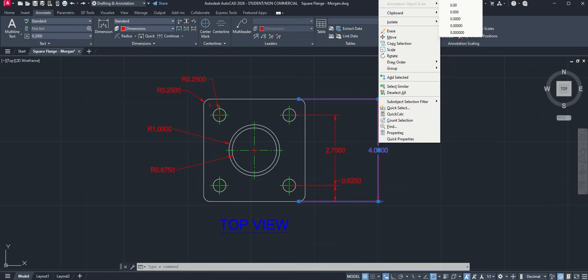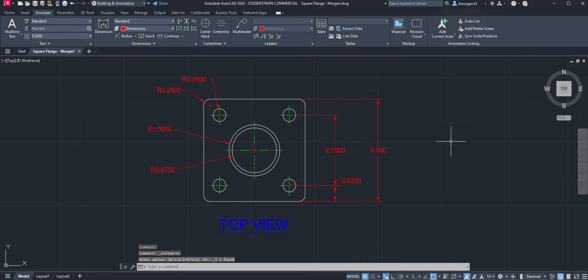There's a quick access, so you can see the dimension, look at this, the style, and then of course precision. You can change that by selecting all of it. So if you want to change from 4 decimals to 3 decimals, we can do that.